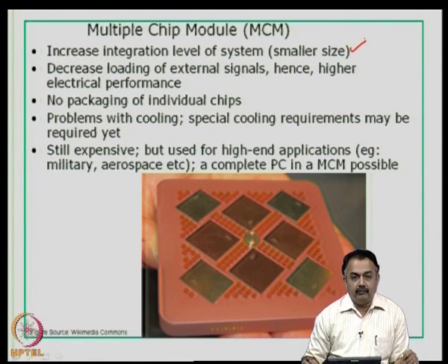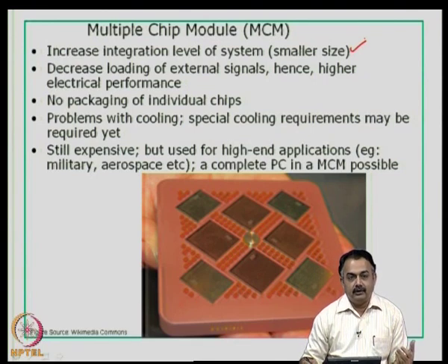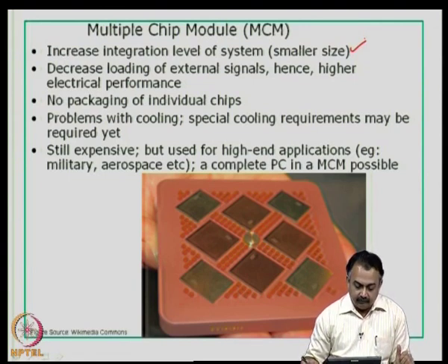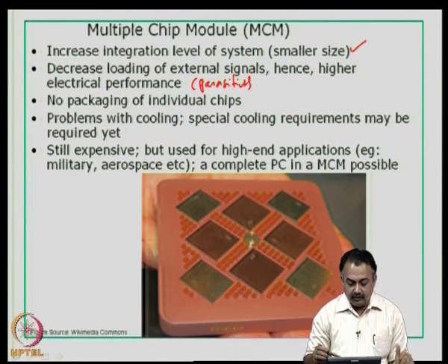Now, electrically, you are expected to get better performance by using a multi-chip module, because it will decrease the loading of external signals, which otherwise, if you look at a printed wiring board which contains individual chips interconnected to perform a common function, the loading will be very high. There can be a lot of electrical parasitics affecting the entire system, and therefore, you will have poor electrical performance.